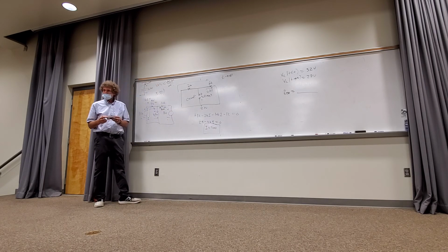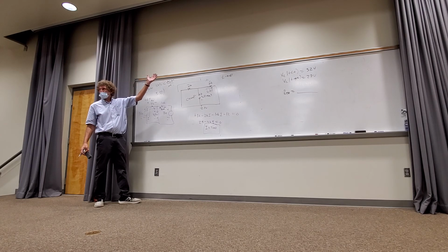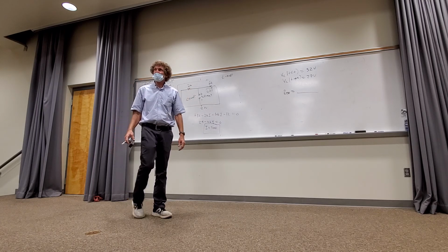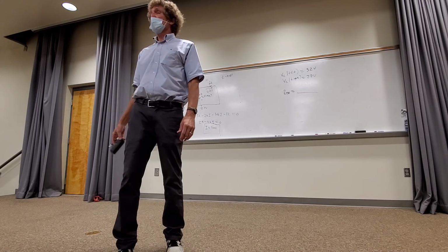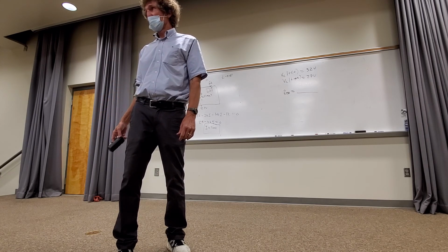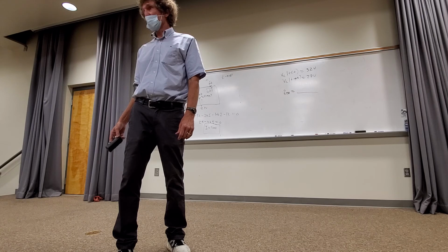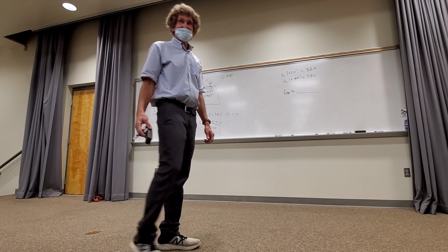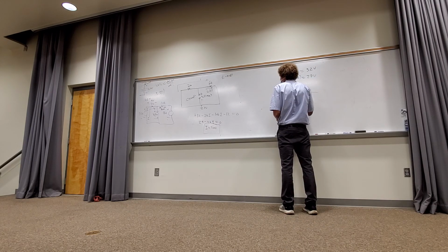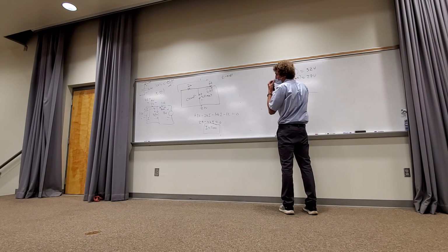Now, what is R Thevenin? Can you see it? Tell me about those 2 resistors. Are they in series or parallel? How many see they're in parallel? I'm so glad I heard you say that. All right, so I got 2K in parallel with 6K, or what? 12 over 8K, correct? Or 6 over 4, or y'all follow me on that? It's what? 3 over 2.